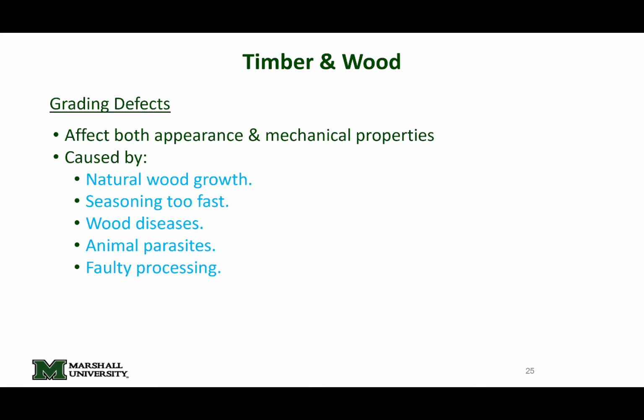Okay, I've got checks in this element. I've got shakes in this element. I've got a little bit of a wane right here. So there are all sorts of defects that are going to affect whether or not it's going to be select structural or number 2. And again, this is coming from the earth. That's just going to happen, okay?